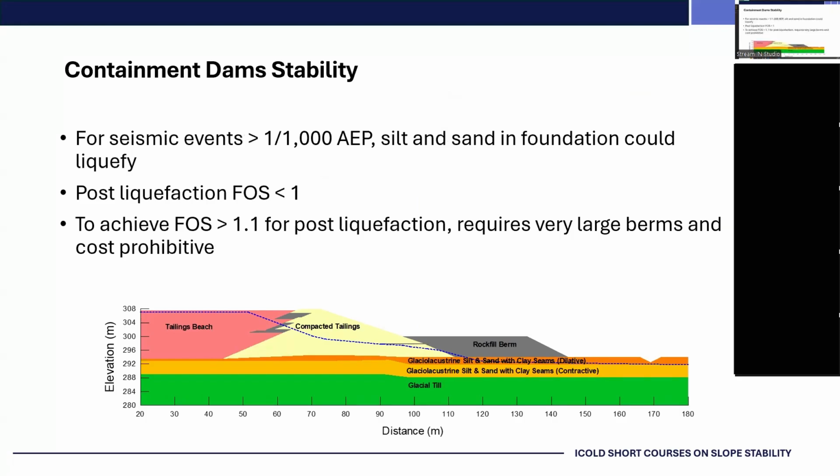So when we're dealing with operating conditions, we're looking at the 1,000-year seismic event. And we have used different methods such as deep soil, which is a site response analysis, which has indicated to us that the 1 in 1,000-year seismic event won't trigger liquefaction down here, but greater than 1 in 1,000 will.